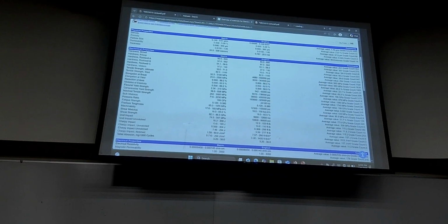What else do you see there? Compressive yield strength, sigma UC, is given. Tensile strength, sigma UT, is given. You see that these are really practical terms that we've been talking about. The density that we need in this part is given in here. You can go for the mid value. The unit should be kilogram, not gram, in SI.